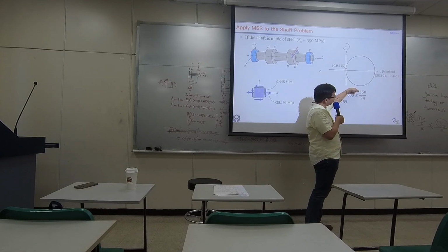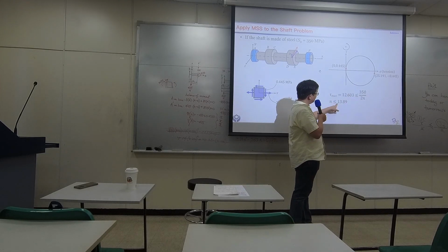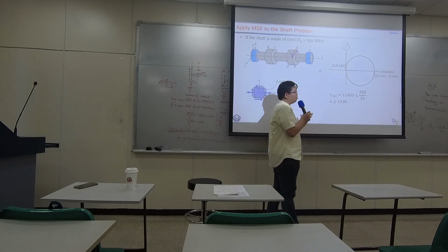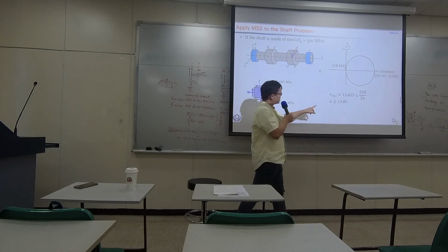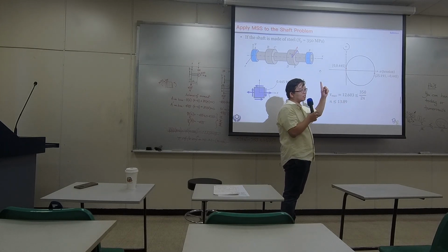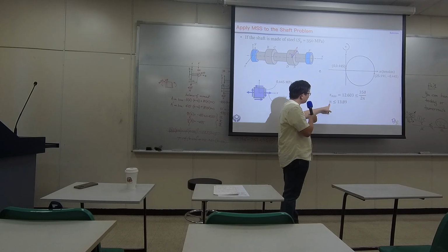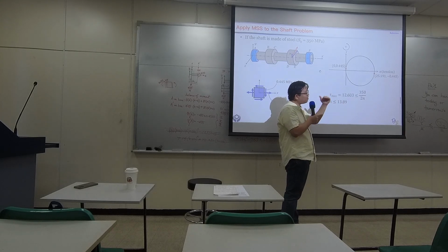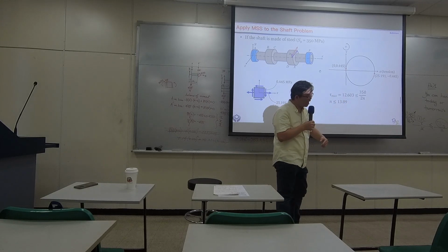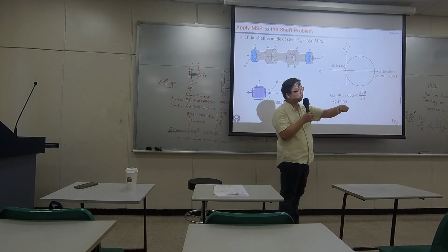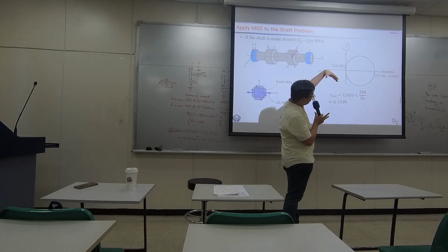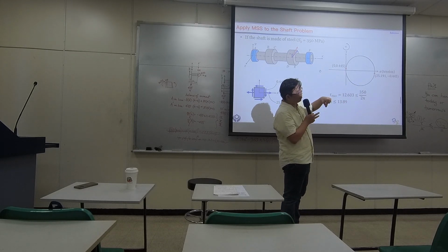If you downgrade this to 200, you just have a lower safety, but your material won't fail, because that value will remain higher than 1. As long as your safety factor is greater than 1, that means your design is not at the edge of yielding. You're far away from it.